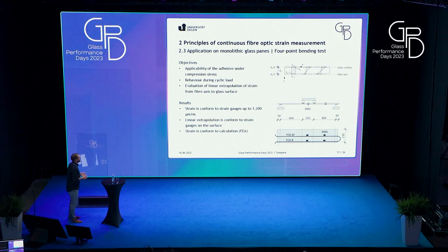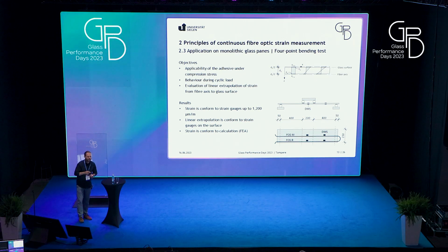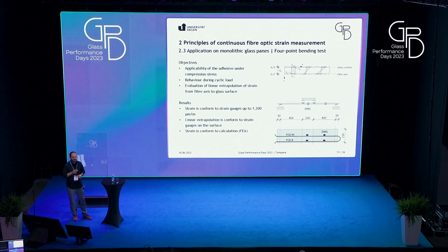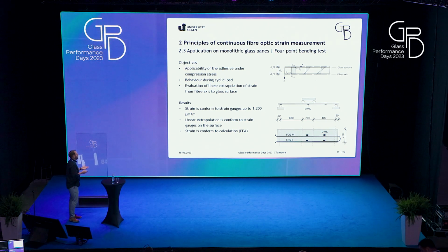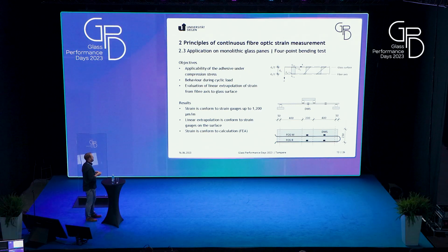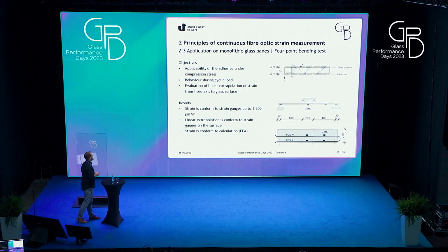In the next step, you have to investigate the behavior under compression stress, but you cannot take any small test specimen made from glass and give compression load on it, because then you have a buckling problem. So it is suitable to use a monolithic glass pane. The test setup is shown bottom right.